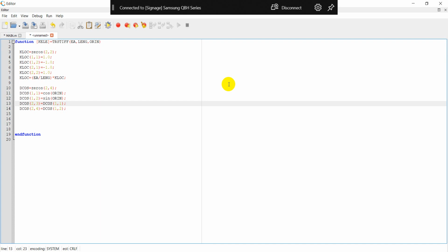You need to reevaluate your stiffness matrix, and as you reevaluate it, you recalculate the K. If you do linear time history analysis, linear means your structure is not changed, then you repeat the K you obtained at the first step. But nonlinear time history analysis is a pain, because if you have 10,000 time steps, you might need to recalculate 10,000 times. Takes so much time. All right.